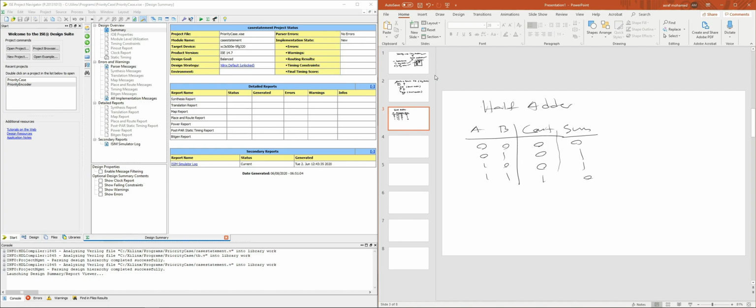If you look clearly, this C out can be represented by an AND gate, and this sum can be represented by an XOR gate. You can see that from the output pattern itself. Now let me first draw the gates. We have an XOR gate for the sum, which has two inputs, A and B. This is for the sum. Then the same inputs flow to the AND gate. This one is going to be C out.